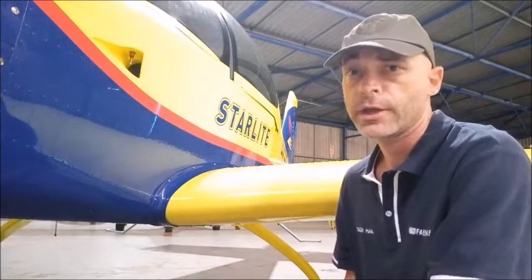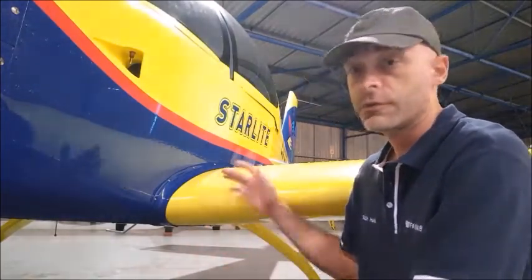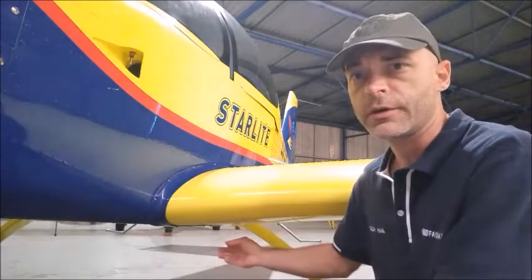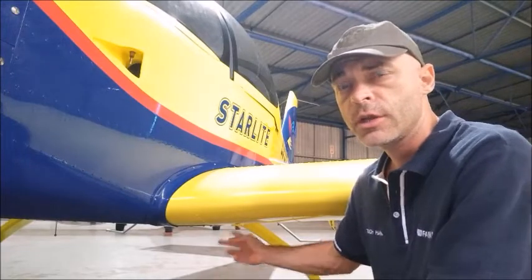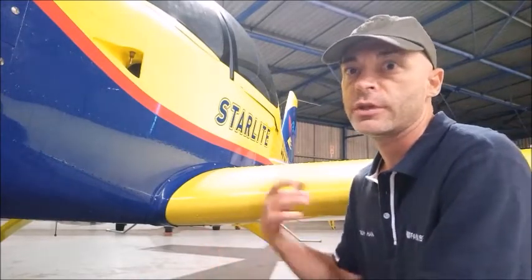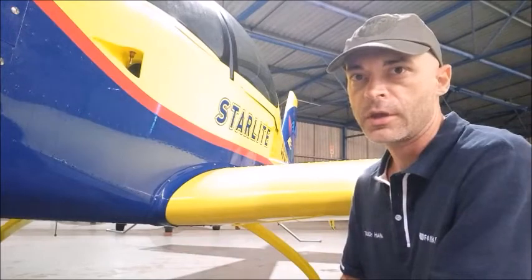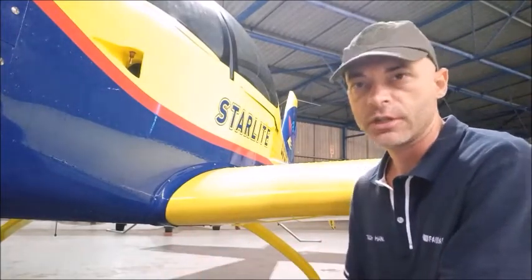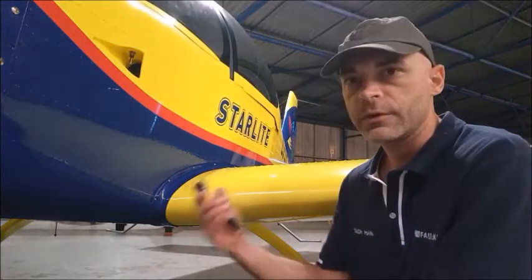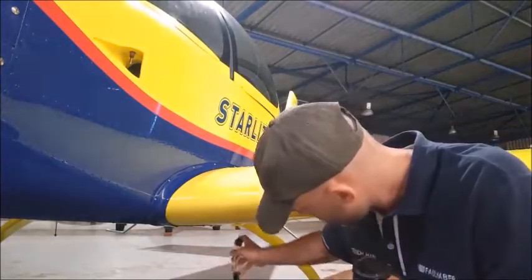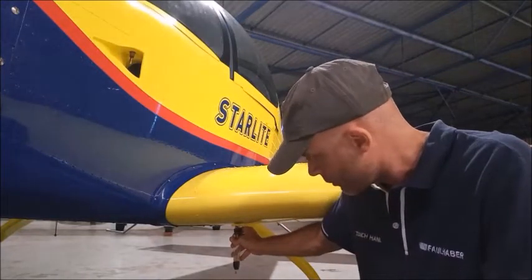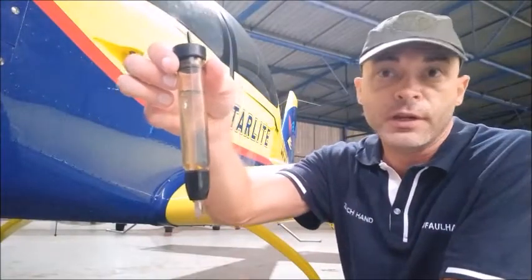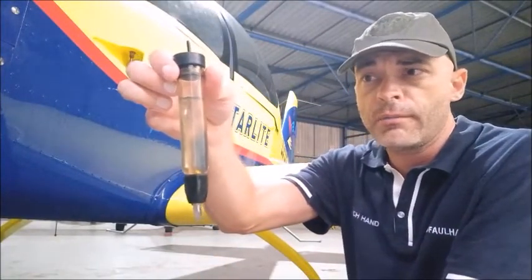Fixed-wing aircraft or aeroplanes have tanks for the fuel within the wings, and there's what's known as a fuel straining point at the bottom. You want to check and make sure there's no water inside of the tanks, because that could be a problem if you're flying and suddenly there's water coming into the engine. To check it, we've got a fuel strainer that we stick into the bottom. We're able to strain some fuel out of it, and this is specifically MoGas or petrol.